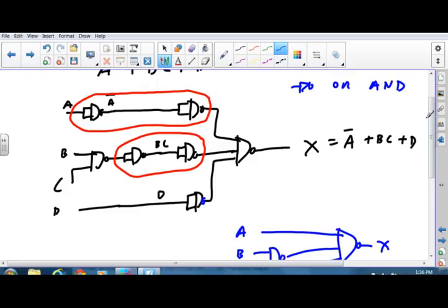Now, there are instances where these gates, we haven't talked about how quickly they do things, but they do things in the nanosecond time frame. So they turn from a 1 to a 0 in 2 or 3 nanoseconds, very quickly. We may want to delay how long it takes for it to change for some reason. And then you'd end up putting multiple inverters together just to delay the circuit. I want to delay the circuit by 15 nanoseconds.